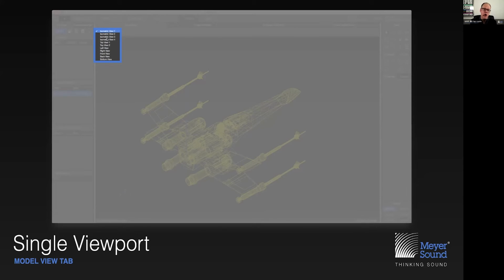and we can choose the camera angle of any viewport by using the drop-down menu in the top left corner, which has several camera angles already pre-populated, but we can also create our own camera angle and store that with its own dedicated name, so that we don't have to massage the camera each time we want to revisit that particular angle.